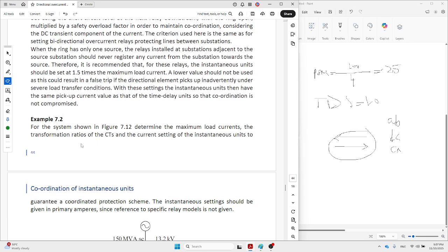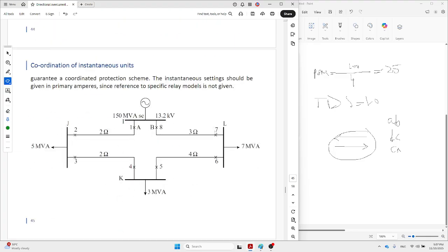Here I provide you another example. This example also helps you to fulfill your lab 2. The network here has 5 buses, while your network has 9 buses. When we are going to calculate and find out the relays, for this purpose you have to consider the fault current and the load current carried from this way to here. Since A is open, for the other one you have to start from this way and reach this point. Assume B is open, or switch 8 is open.